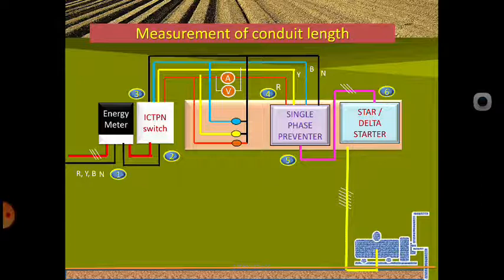What is the length? Here also we are using the flexible metal conduit. We can take the meters from 6 to 7 as the amount. So how much length do you have to take here? Here the 6 wires have to be drawn through the metal conduit. Now 6 to 8 is the other length.